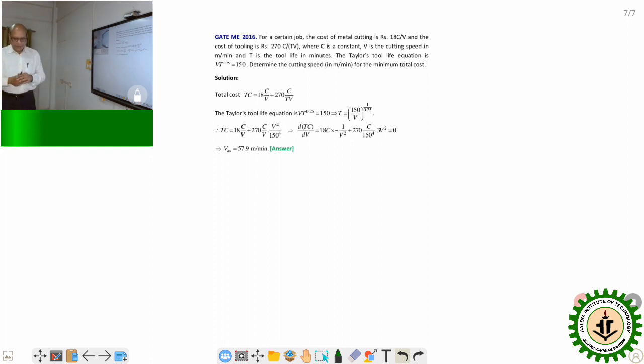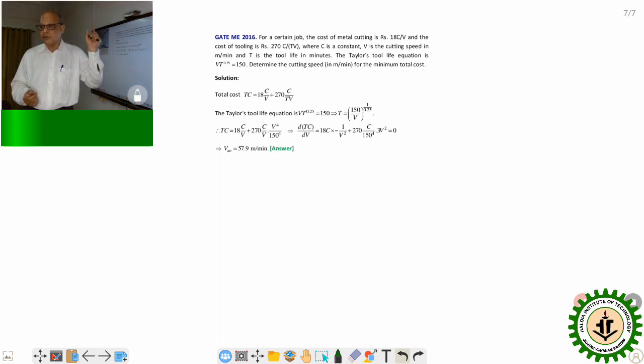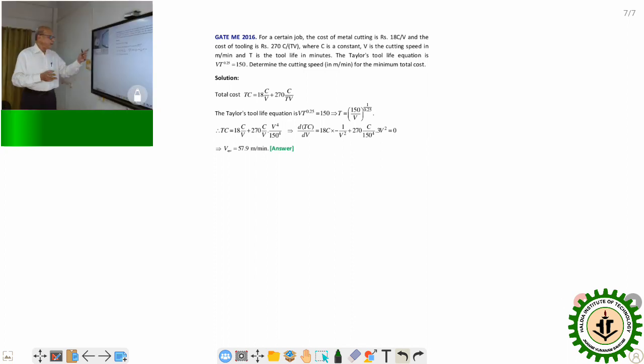In case of CNC, there is an advanced module which I had not considered, called adaptive control. So adaptive control with optimization is how the operating variables, that is speed, feed and depth of cut, can be regulated or optimized so that any objective function, that may be maximizing MRR or reducing cost, or improving productivity, can be maximized or minimized according to our requirement.